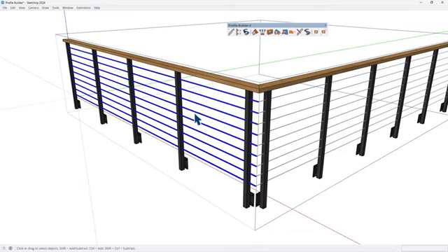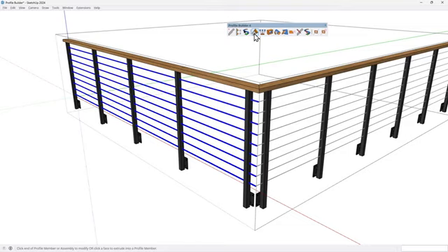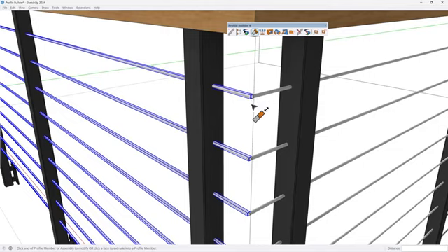One way to pull these in is to select all of them and using the extend or split profile member tool in Profile Builder. So I'm going to click on that and notice I can pre-select more than one profile. And as I hover my cursor over one of those, you're going to see that little arrow indication. And when I click on that arrow indication, that's my starting point.